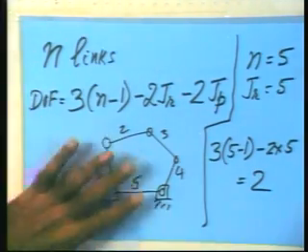So the formula also gives you the degrees of freedom, but you can also find the degrees of freedom by drawing. One of the reasons why I keep repeatedly telling you to draw it is that it gives you a feel: how many angles do I require to draw this picture? That is the number, provided the lengths are given. Remember that. This is a closed kinematic chain. I could replace these revolute pairs, all of which in this particular case are revolute pairs.